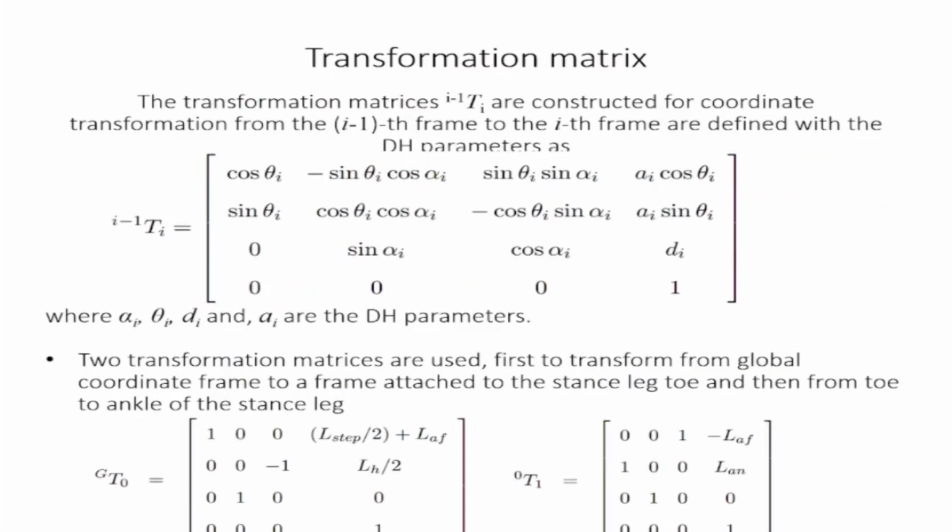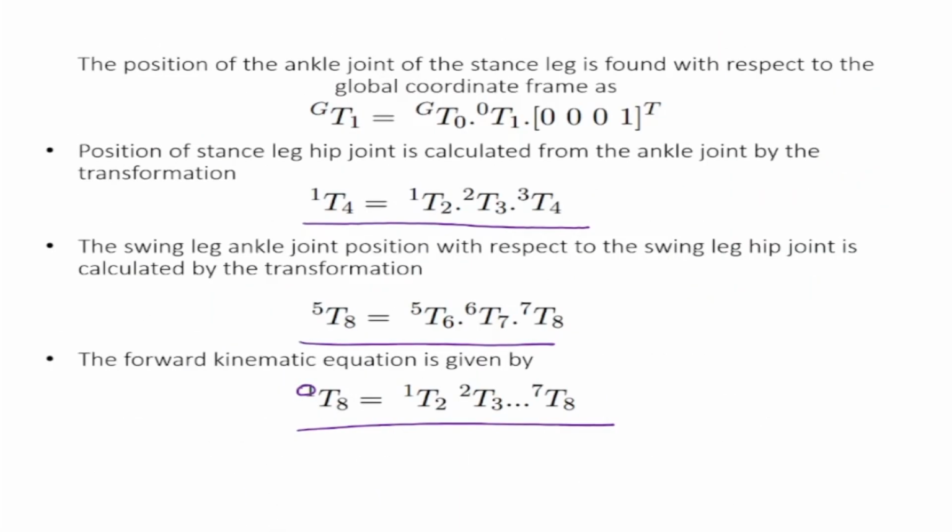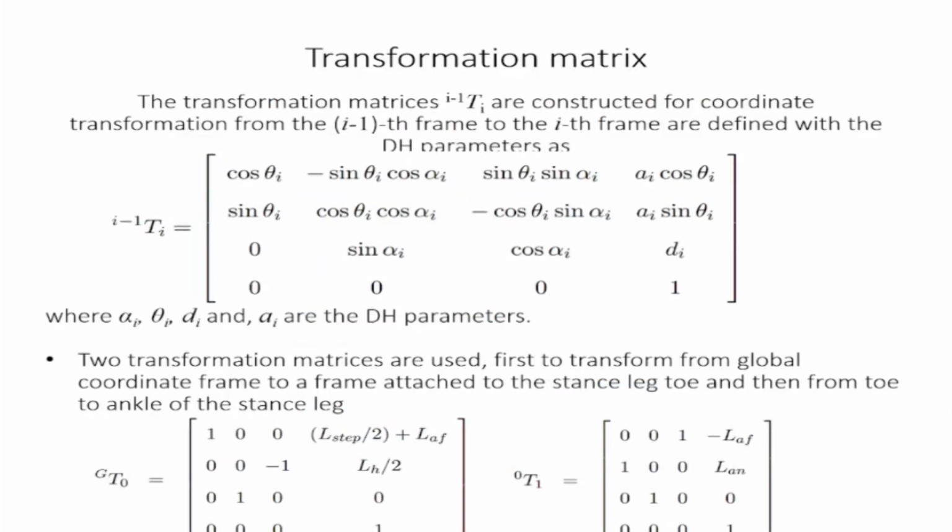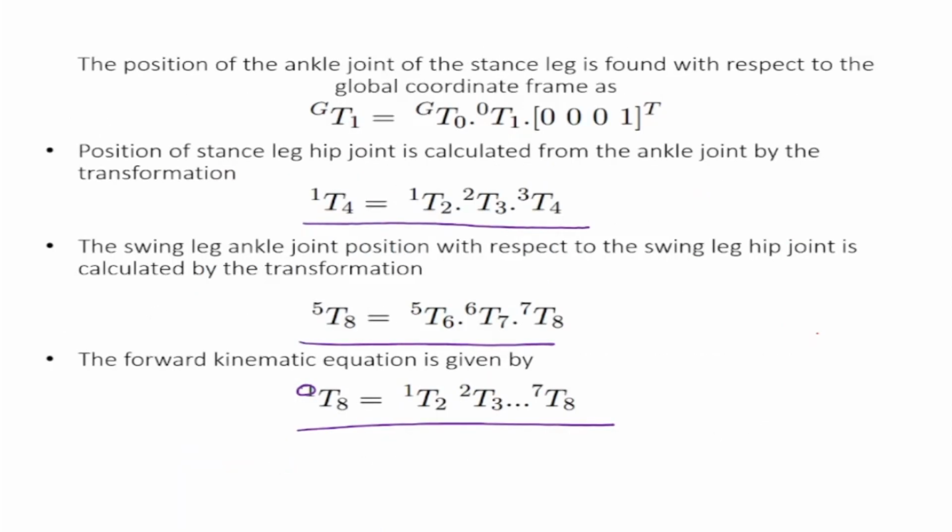So we put our DH parameter table, and then we find the total transformation matrices that you know how to do. We define our generalized matrix, and then from the DH parameter table, we can find each of the transformation matrices, which is going to relate T08 to the last matrix. This is what we are going to multiply and get. So I get the relation between the last frame and the 0 frame from here.